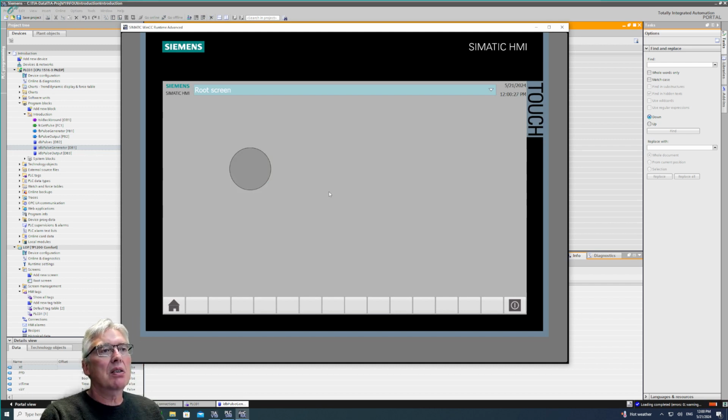So this is fast flashing red. You could use this for errors. On an HMI system, the only time you use red color is for error. You can't use red color for anything but false. So that's just the way it is done.